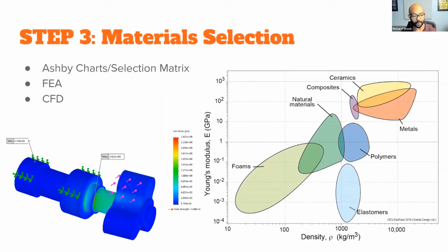To give you an example, down on the bottom left here, we have a shaft with an impeller attached to it. This is a project where we were developing a high pressure version of a pump that we already produce. We found that the shape of the rotor was best to be this tri-lobe type shape, because it distributes the force from the suction side to discharge side a lot more evenly than if we were to do a bi-wing design or a more complex lobe design.